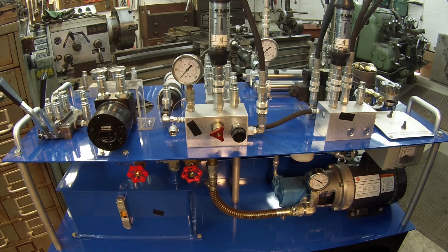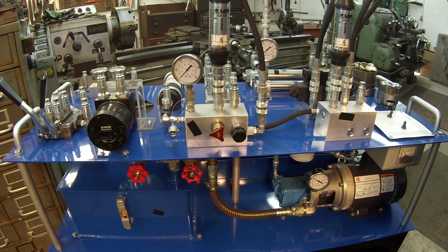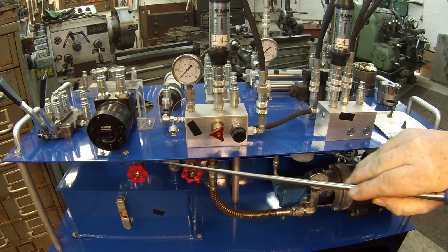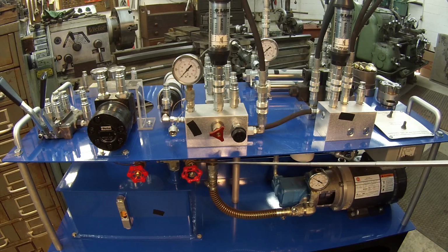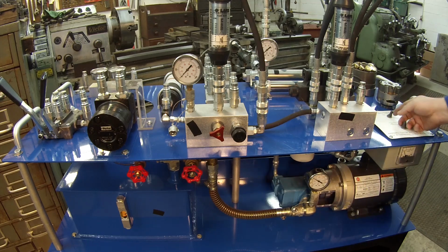What we want to do is show what cavitation and aeration sound like in a hydraulic pump, so you'll know what to be listening for. And the way this little demonstration unit is designed is so I can show, this lets air in right here, and this actually shuts my flow off right here from my pump, and you can hear what those things sound like.